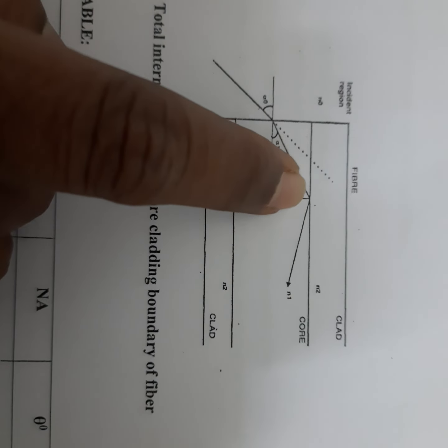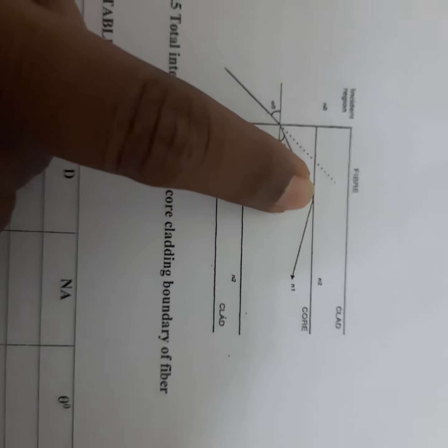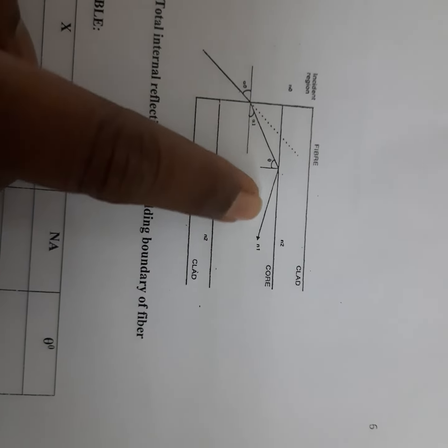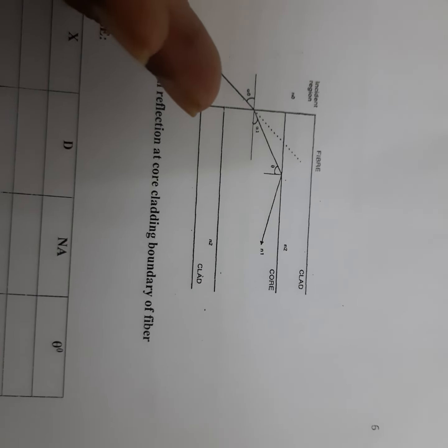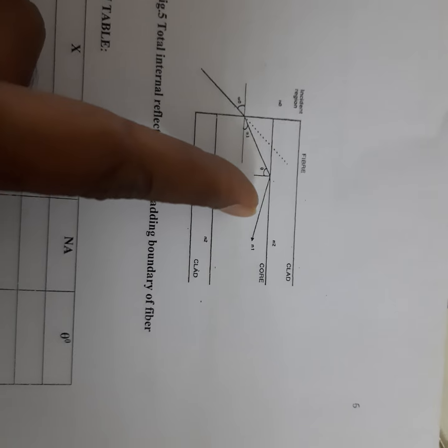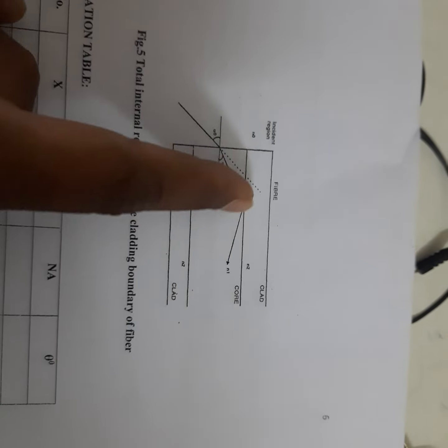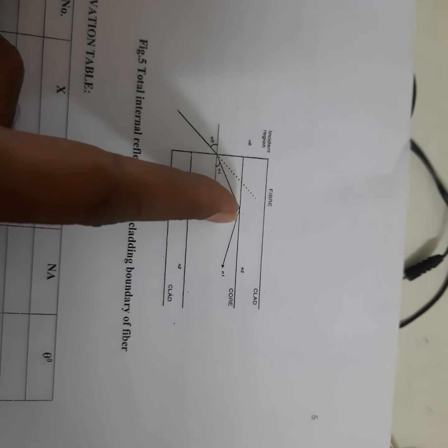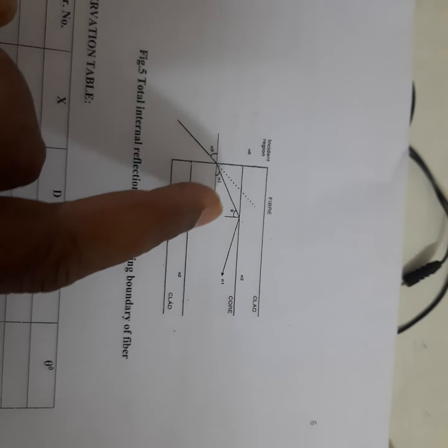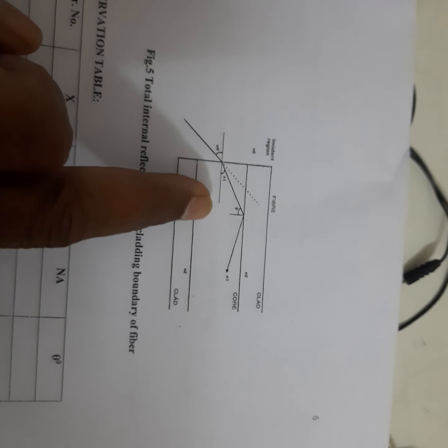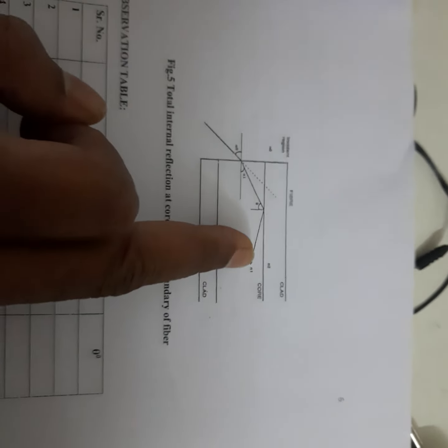So this is your core part. Once the light enters the optical fiber core, it hits the upper part of the core wall and gets reflected by the principle of total internal reflection that we studied, right? When the incoming ray of light makes an angle greater than the critical angle, the ray gets totally reflected in the same medium and does not go into the cladding. This phenomenon is responsible for the light to travel inside the optical fiber. Such a series of reflections takes place, and the light ray gets confined and travels inside the optical fiber. This is the basic principle of how light enters the optical fiber.